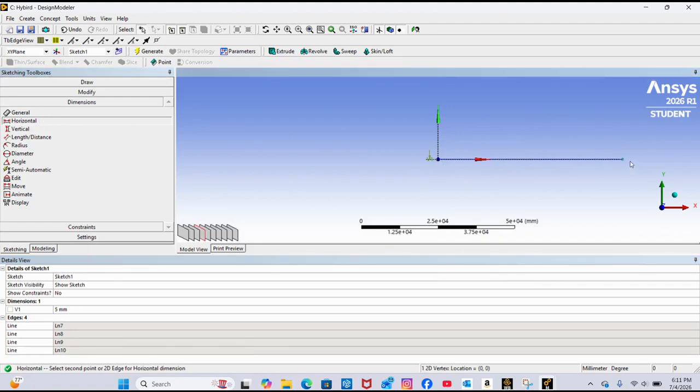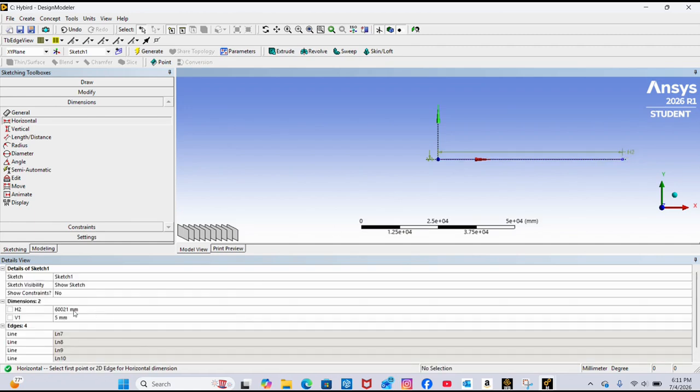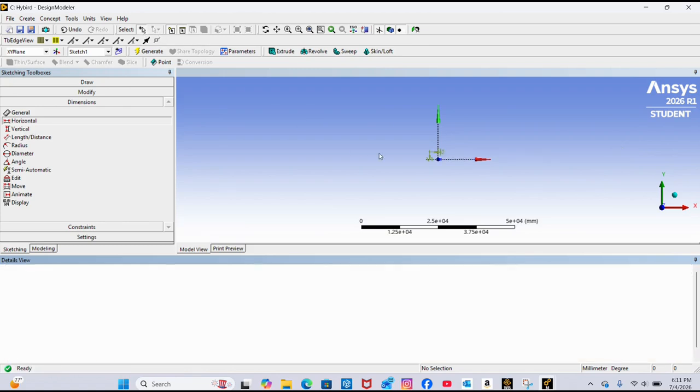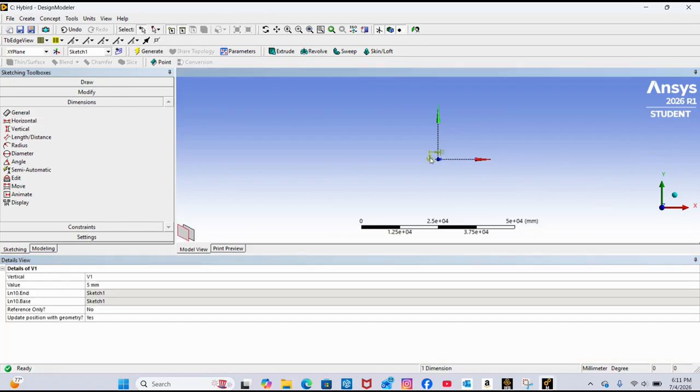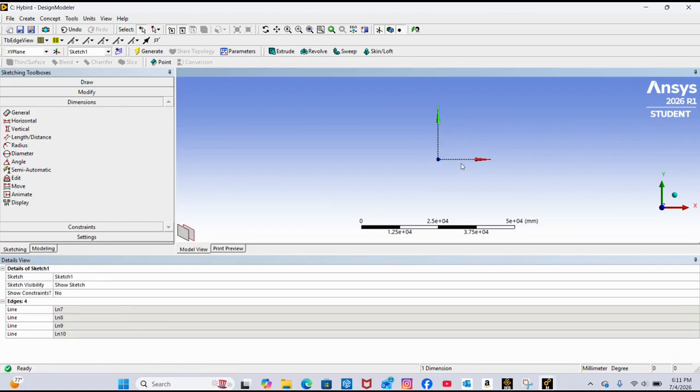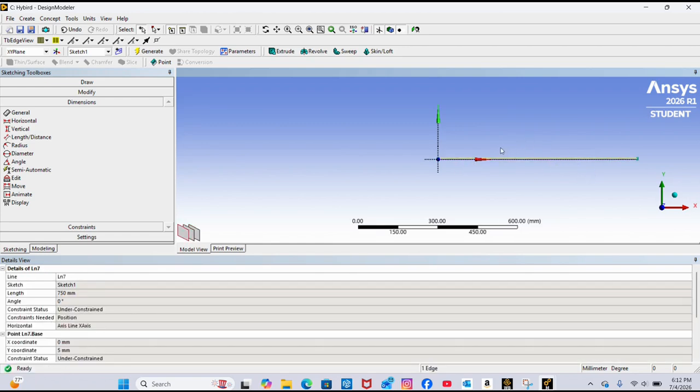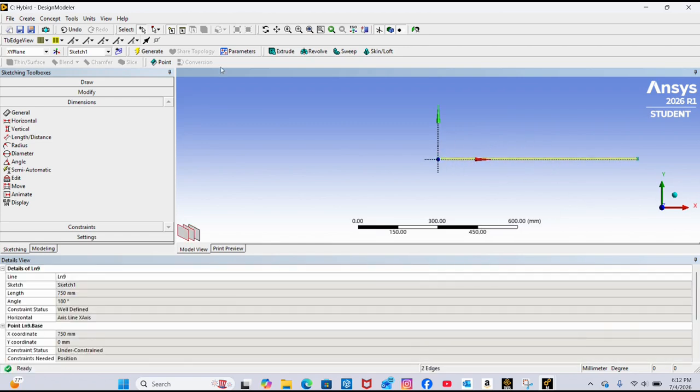You're going to double click the ends, drag it up, and you're going to put that as 750 millimeters. Now, personally, I normally try to delete these after I'm done because you only really have them to set the distance. So I'm going to delete these two, leaving you with your rectangle here. What I'm going to do is select it, so you see the whole thing selected.